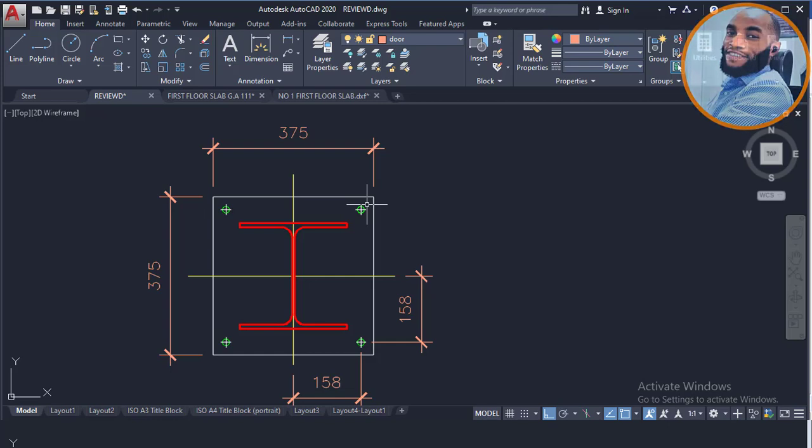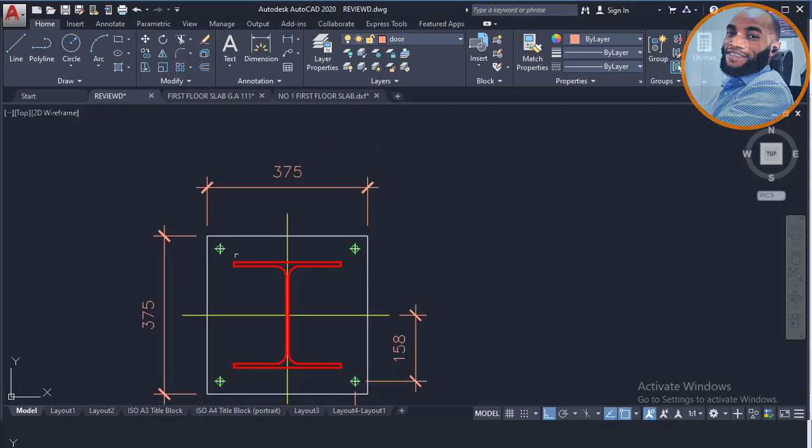You don't just assume any kind of figures. As you know, this steel member here, which is the column, is giving us 250 by 250. You will not just come and assume, let me say, 413 or 400. No, there is a good assumption you are meant to make, like 300, 350, 325, 375, 400, 450, 425. Don't just go and assume 412 and all that. Those values are odd numbers, and they are not good.